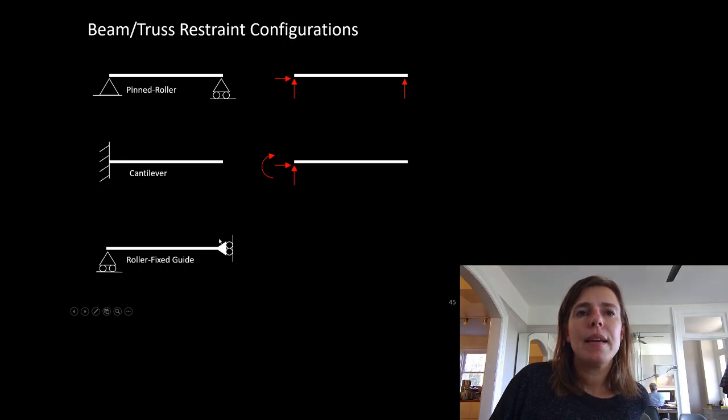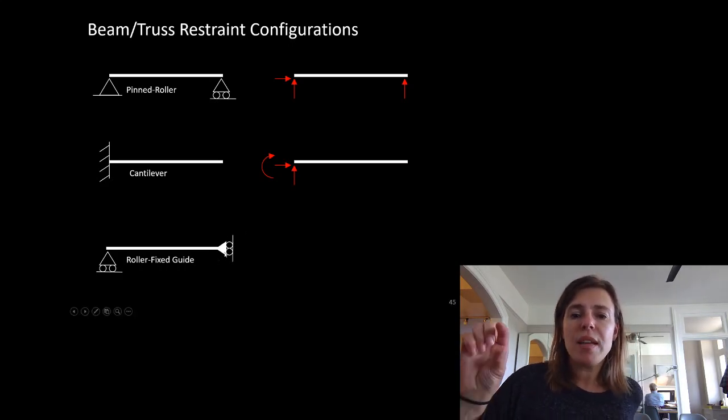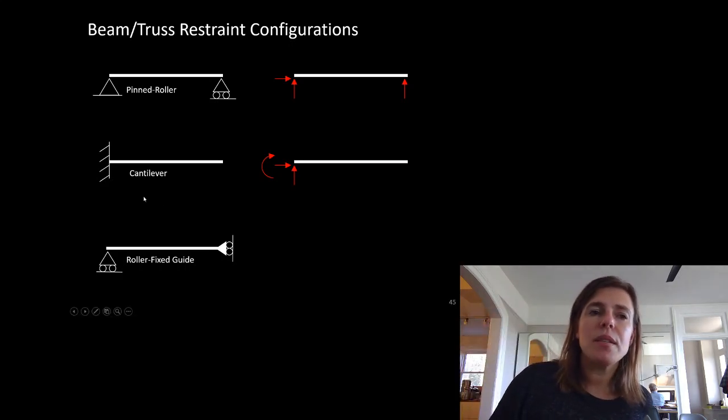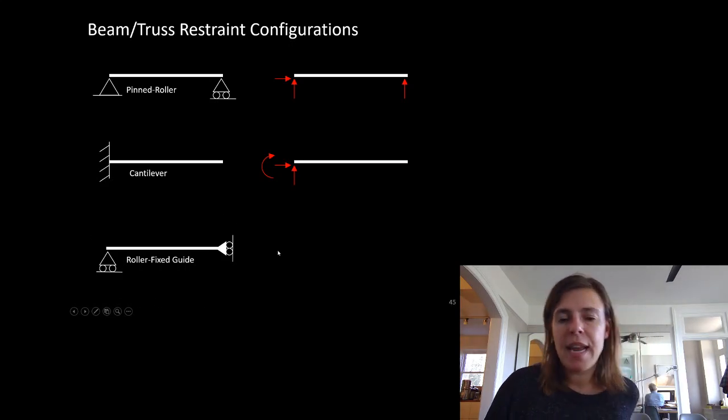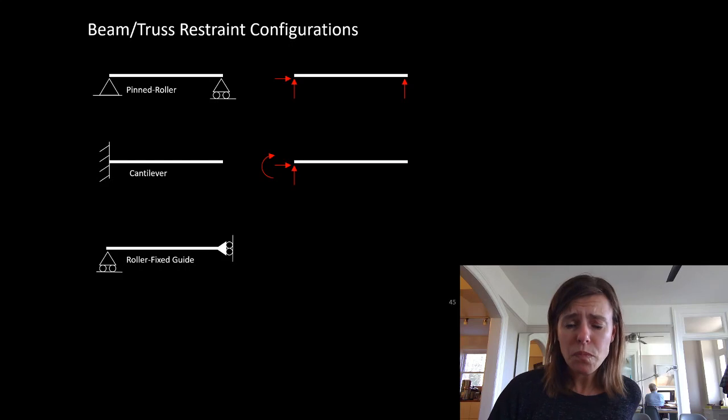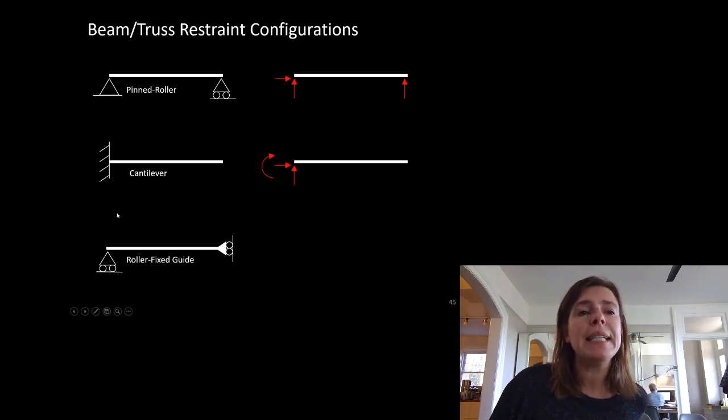But this, if you guys remember, that solid triangle represents a moment connection. So we're saying that even though this can slide up and down, we're going to detail it in a way that it stops it from rotating. This would not be a fun connection. In fact, on the Goldring Center for High Performance Sports, which I shared the drawings for with you guys, we originally had to detail this exact system.